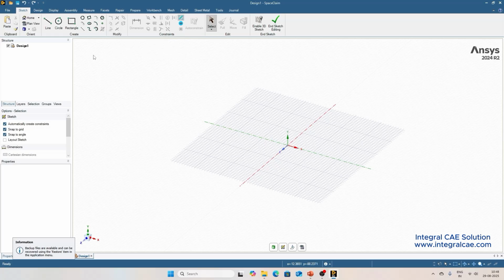At the beginning, you can create the sketch on this grid that is displayed. However, in case this grid is not visible, then you need to create a plane to start the sketch. Please remember, to create a sketch you would either need a plane or a planar surface of the existing geometry. Right now, let's look at the option of creating a plane for sketch.